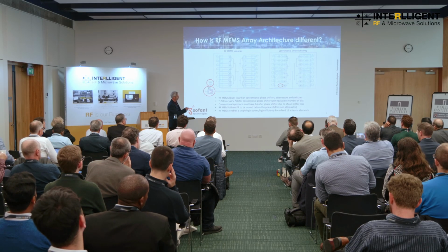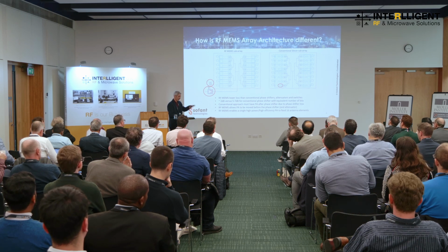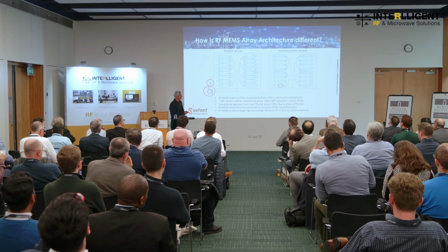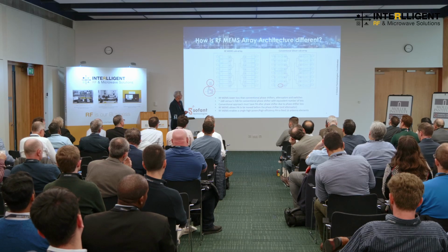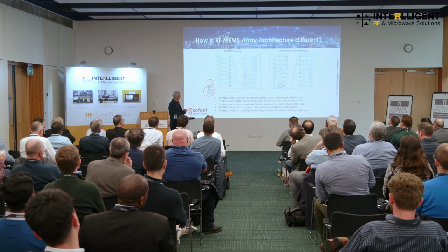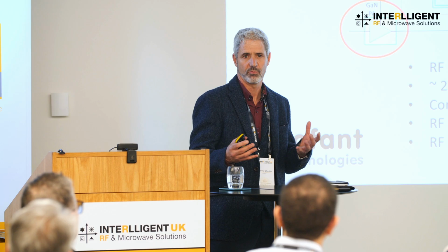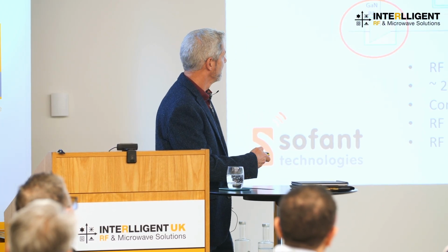So this is a module we make. This is a kind of traditional approach: people make a module, it drops onto your motherboard. Normally they make 4 paths into a single chip, sometimes 8 paths into a single chip. We make a single device driving 1 antenna. The reason it's showing 2 antennas here is to demark that we've got RHCP and LHCP in this antenna, so you switch between them depending which satellite network you're operating on.